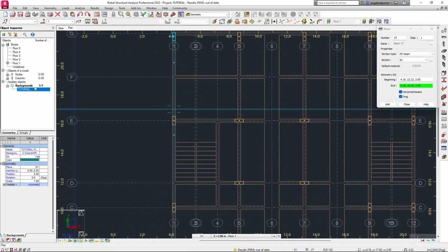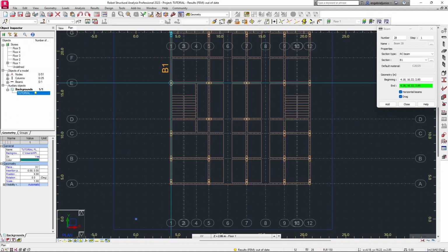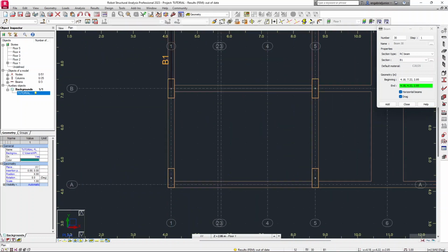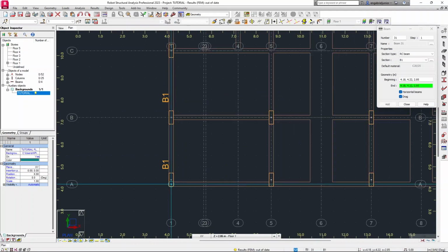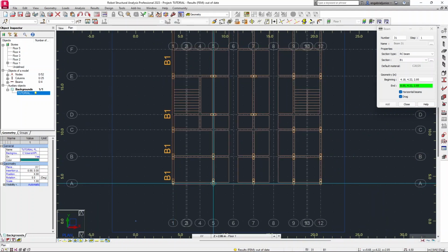I can decide to just take it from there to here. Like beginning with the main beams, or rather the beams which have the supports at the columns, so that when I'm modeling the internal beams, or the beams which don't have all their supports or either of the supports at the columns, at least I already have the beams which will support them. So like that.